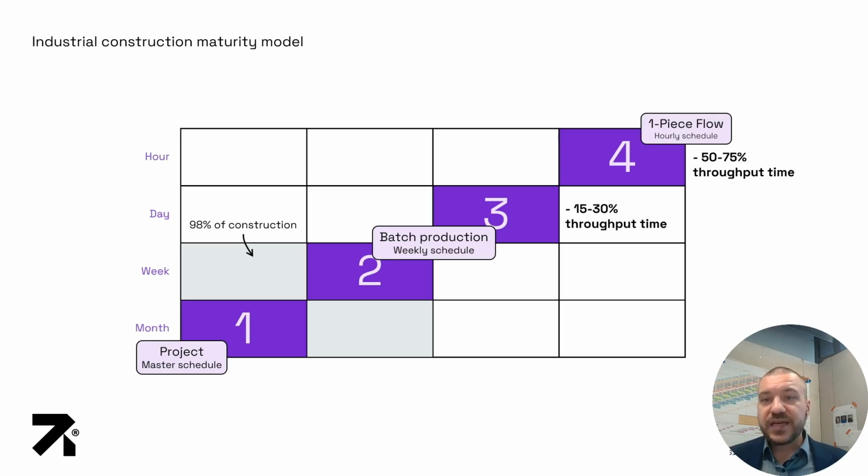Now the steps you can take today: I would assume that almost everyone starts from the monthly or weekly level, because that's where construction is. The first part is that we take those crews who still do this monthly or bi-weekly planning and control and standardize everyone to work on a weekly level. Require that from every single crew. It's completely doable. It makes production more responsive and more predictable.